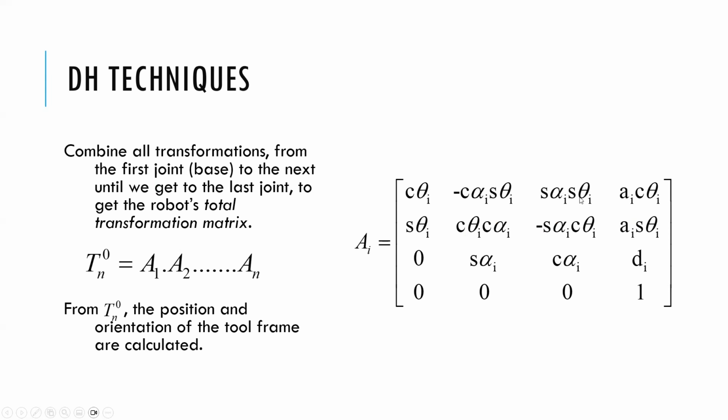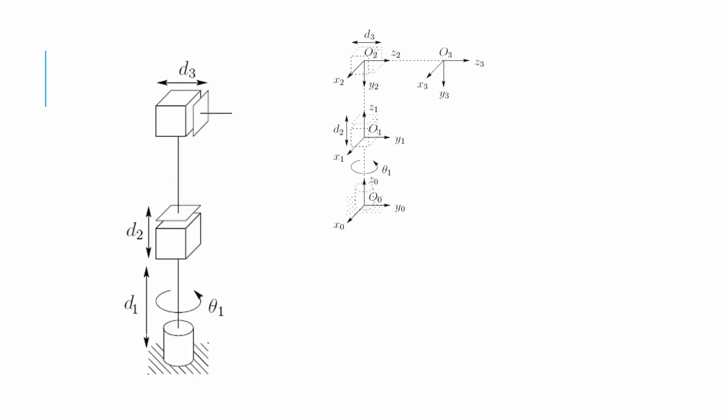I don't have to actually do the dot product, but I can do a cosine times the theta, a sine times the theta, and compute that. If I'm interested in the X, Y, Z position, it'll be A1 times the cosine of the angle, and A1 would be a fixed length in your system. So one of the advantages is that the computing power needed is less.